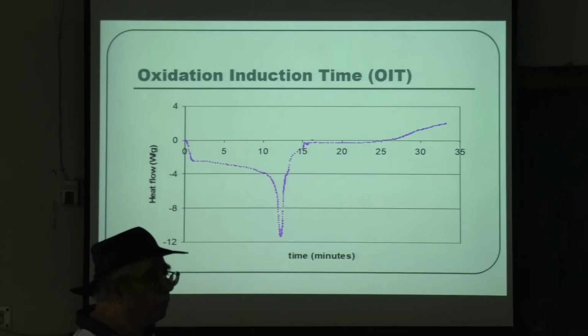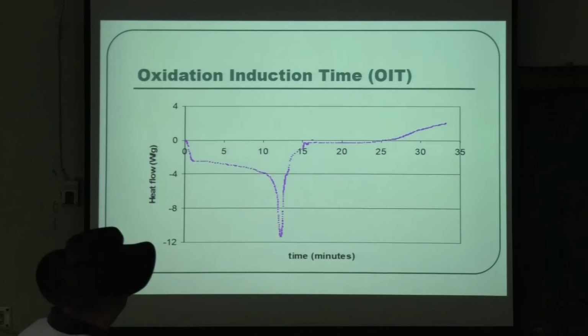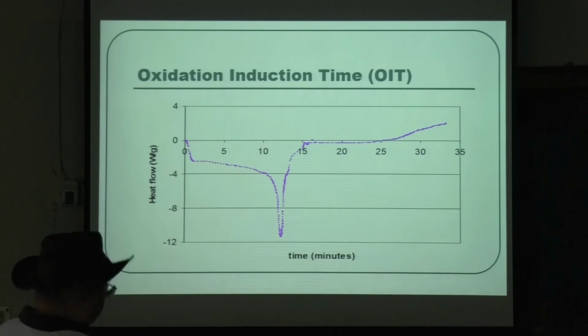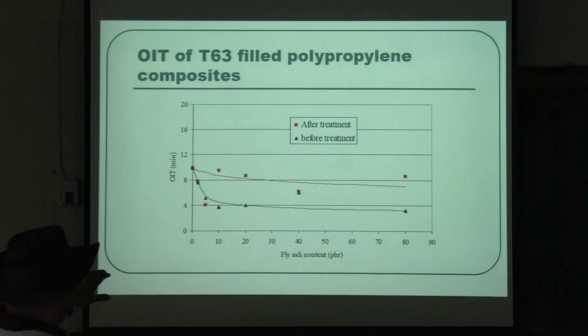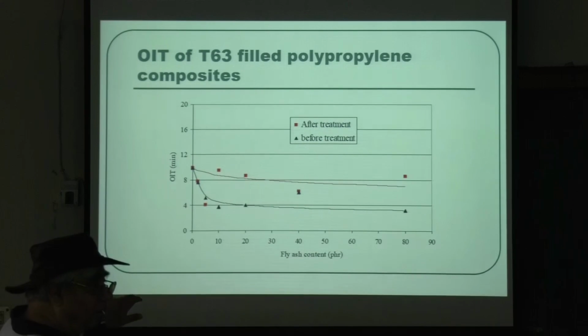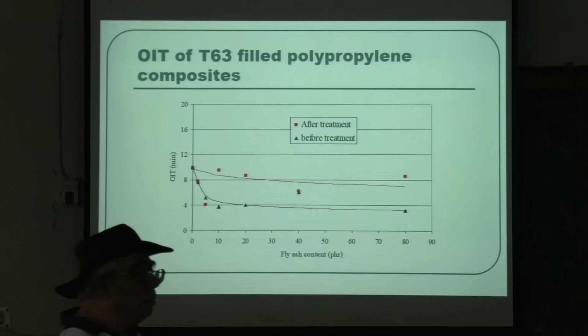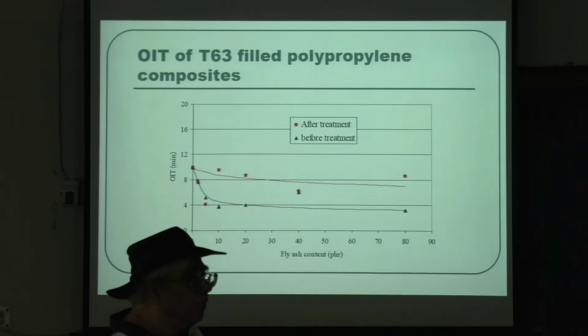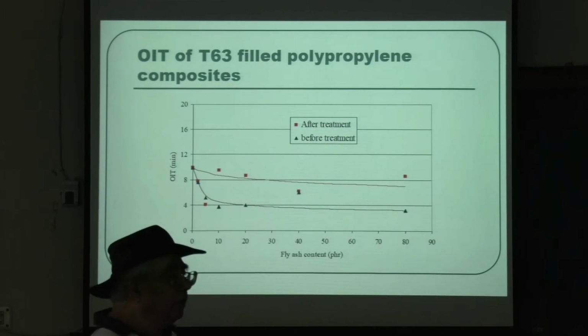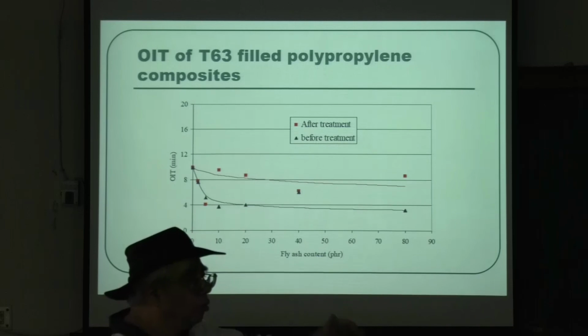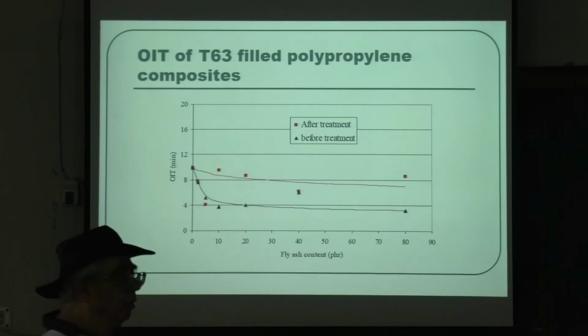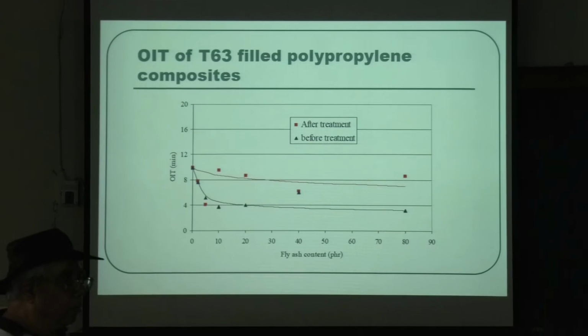Now they are looking at the properties of the entire material, oxidation induction time. The way I look at it, it shows that it can withstand more oxidation. Maybe because the coating is giving some copper on the polypropylene also, so it is preventing its oxidation as a function of time. So it takes more time for any oxidation to start. And I think it's because of the coating. All right? But that was a good question.